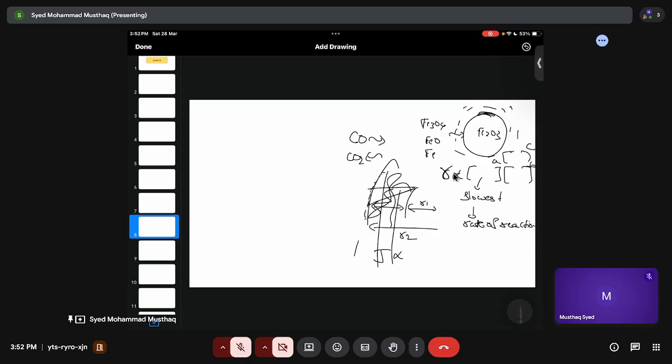More technically, you can say the concentration layer or the diffusion layer, you are trying to remove that. Once you remove the diffusion layer, that means you are removing this concentration gradient. If there is no concentration gradient, the carbon dioxide can easily come out. That means in the fluidized bed reactor there is a very fast mass transfer rate and very fast heat transfer. So that is more suitable.